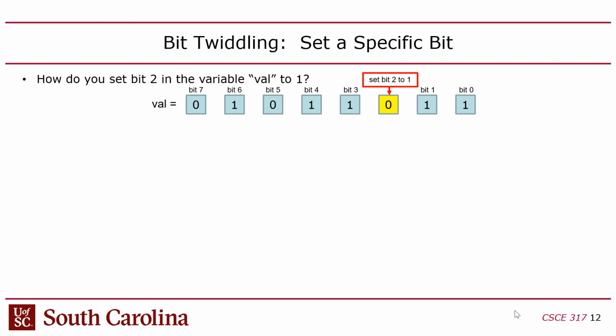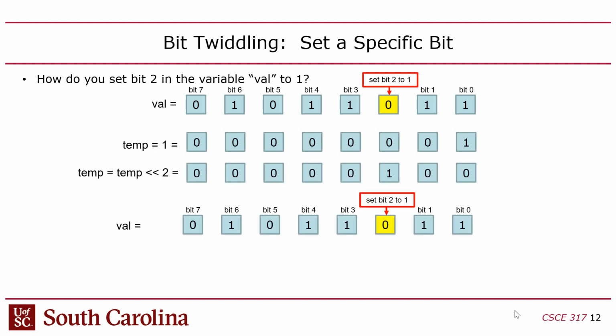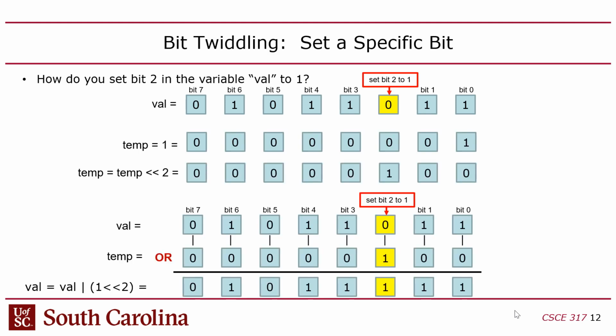The next section is bit twiddling, where we talked about how to manipulate single bits or ranges of bits within a word using C. But of course C, as you guys know, using C is very similar to using assembly language. It's such a low-level language. So we talked a lot about that because when you use programmed I/O, each of the bits in the values you're doing programmed I/O with often will represent specific flags, right? Like you read a flag from the keyboard peripheral and it'll tell you whether someone hit a key, that sort of thing. So you have to be able to extract bits.